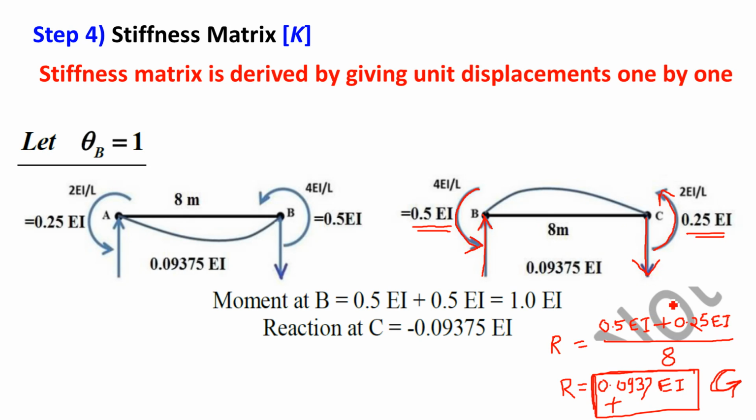Now suppose in any problem you get this answer as a minus, R equal to minus. In that case, minus means clockwise, so the reaction couple will be anti-clockwise. Anti-clockwise means left downward, right upward. This means it is an anti-clockwise couple, right? So anti-clockwise couple means left downward, right upward reaction, and clockwise couple means left upward and right downward. In our case, it is a clockwise reaction.